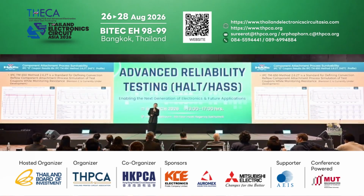Sometimes it can be a 230 degrees C or 245 reflow profile for leaded PCB, and 260 for lead-free PCB. So we have different assembly process simulation temperatures.